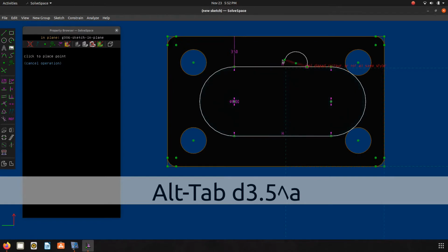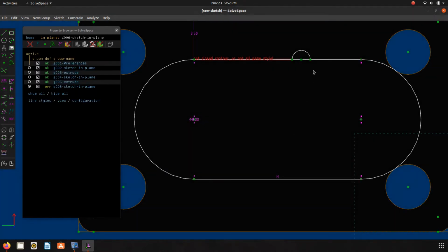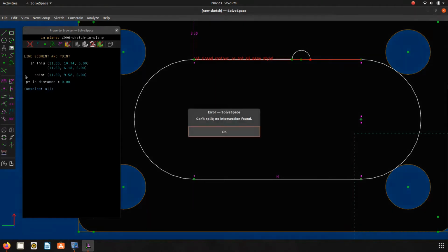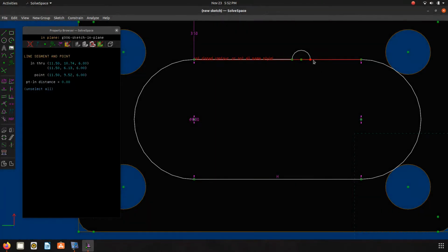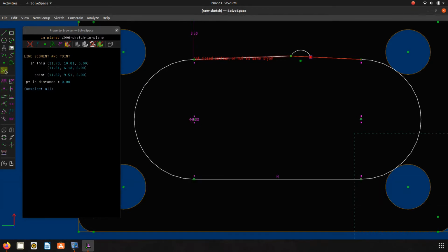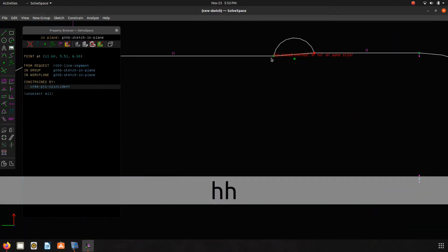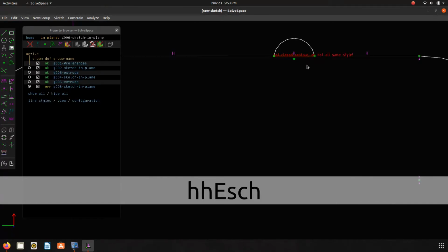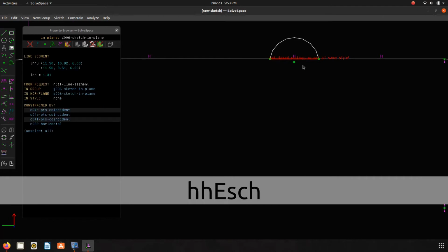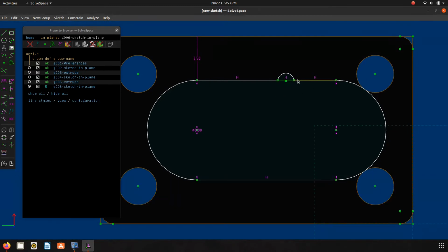Then we need another arc here. And we gotta do this guy that splits it. Put it back, that, and we will go ahead and split that. Now, the reason we gotta split that one is because actually we can just make this line horizontal. The reason we have to split that is because we need to be able to make this green, or make it a construction line, because otherwise you would just have a solid line there.